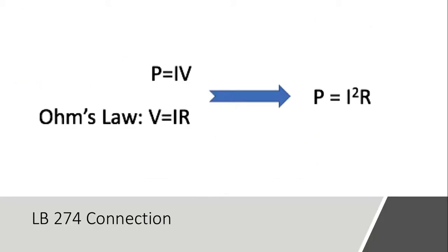So an interesting aspect we can look at with the power grid is the voltage changes that happen throughout the process. At the beginning of the process, the voltage is increased greatly before the transmission lines, and then at the end of the process, the voltage is decreased greatly before the distribution lines. So why does this happen? The reason that this happens is because we want to minimize the amount of power loss due to resistance.